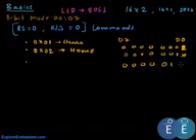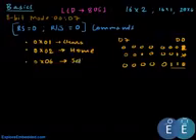If you want to display a letter on the LCD and increment the cursor position, these 2 bits will be 1 and 0. To know why this is 1 and 0, please watch the previous videos. So this would be 0x06, and this sets the entry mode.